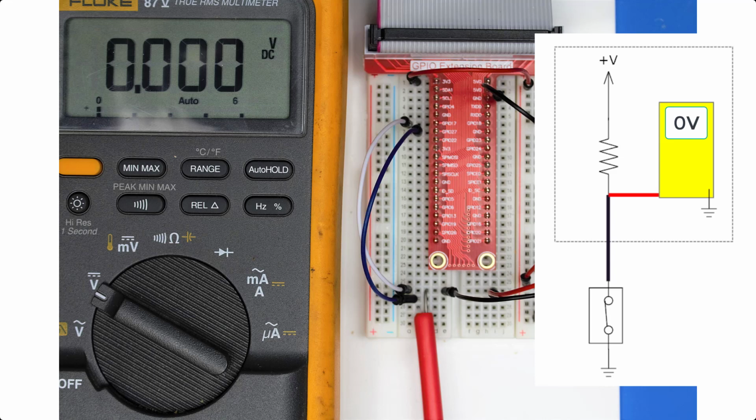This is how the computer identifies that the switch is in the closed position. Using a pull-up resistor, it knows that a value of 3.3 volts, or a little less than that, is the off position. Any voltage that is low, like 0 volts or a little bit more than 0 volts, would indicate that the switch is in the on position, thereby verifying and understanding what the condition of the switch is so that it can determine what action to perform next.